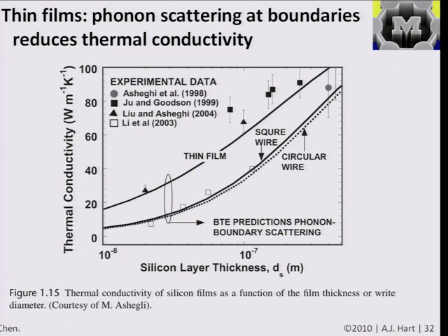And the thermal conductivity of bulk silicon is around 150, just so you have that in mind. And you can see that around 10 nanometers, the effective thermal conductivity is only around 20. And then as you start increasing, it begins to approach higher and higher. And even at 100 or 300 or 400 nanometers, it's still 50 or 40% lower than the bulk value. And eventually, if you were to take this out to, say, a few microns, this would level off at 150 or so.